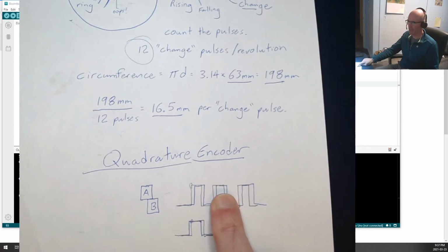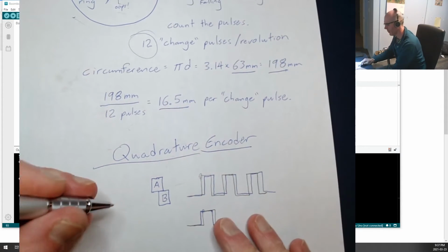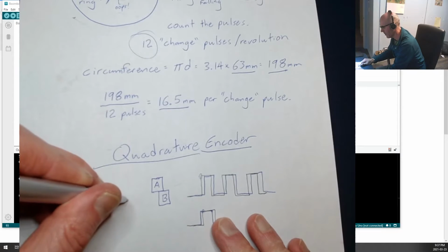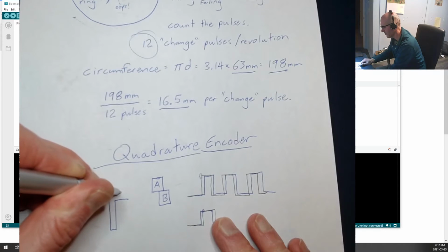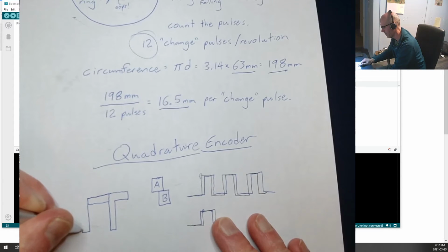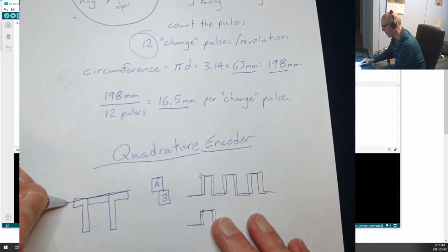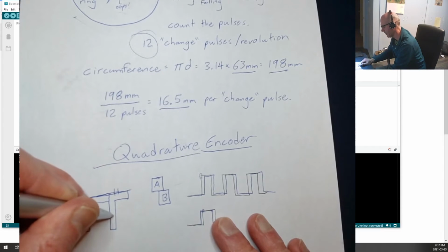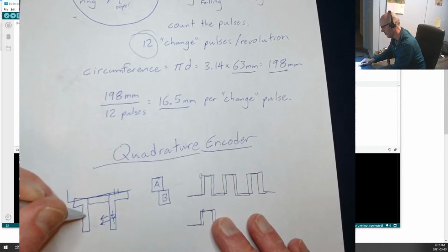You'll also tend to get a lot more crisp, nice edges like that, because instead of using a reflective encoder, a lot of commercial encoders will use a disc with slots in it, and they'll use a transmissive sensor. So what you'll have in a transmissive sensor is a base, something like this. Actually, those would be joined together. In our case, our circuit board would be right up here, and our LED would be down on this side, or the other side, it doesn't really matter which side the LED is, and it would be transmitting light over to our photodiode on this side.